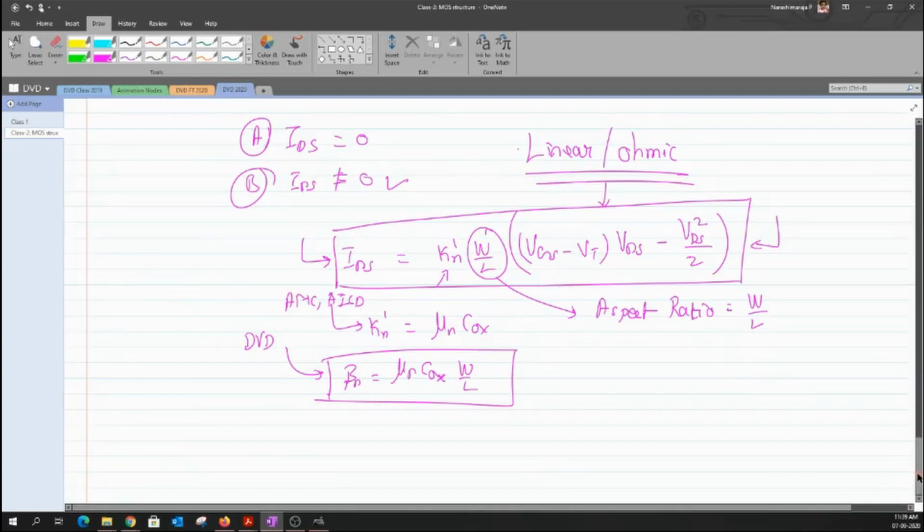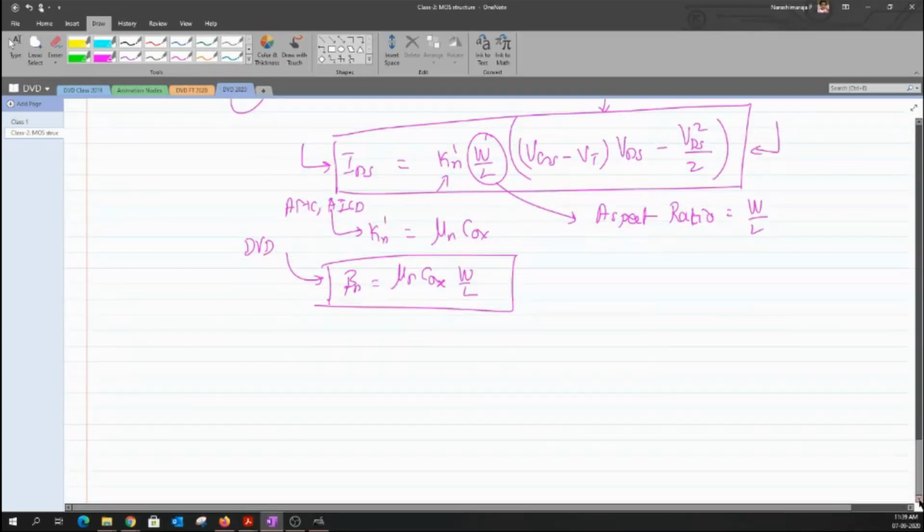And we say that our transistor is in the linear regime. Now let us go for the final case, where the value of VGS is greater than VT and the value of VDS is greater than VDS sat. Now, obviously, we have some sort of positive potential difference between the source and the drain, due to which we have already seen that the current is no more equal to 0, but rather we have some current that flows between the source and the drain.